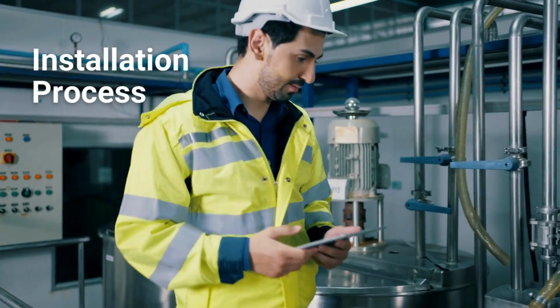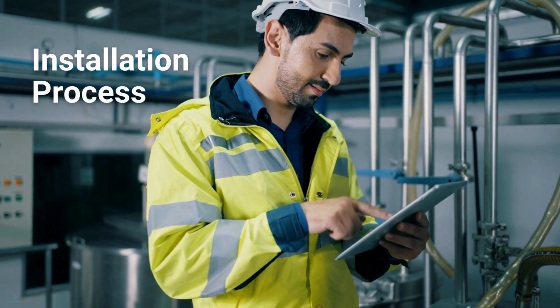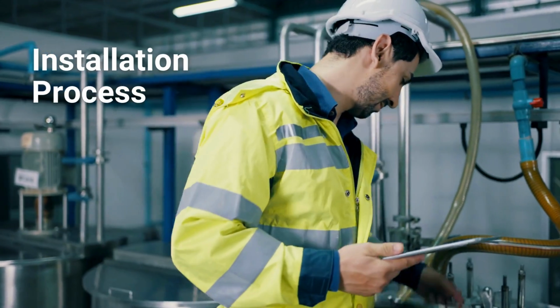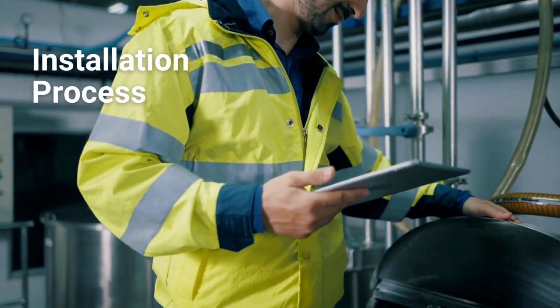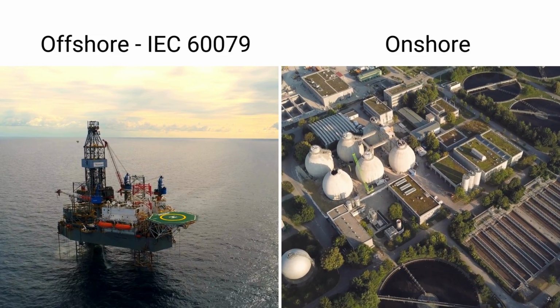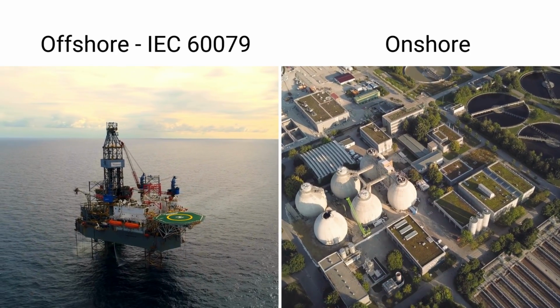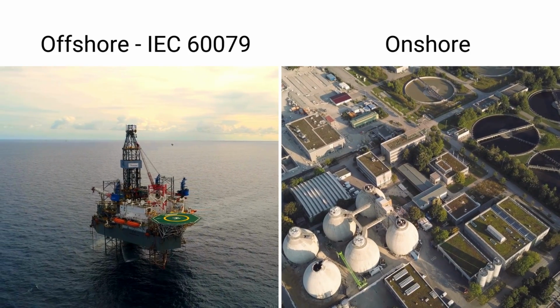Next up is the installation process. Once the design is finalized, the installation phase begins. This requires meticulous planning and coordination with various teams, including electrical, mechanical, and network engineers. For offshore environments, compliance with international standards like IEC 60079 for explosion-proof installations is mandatory. Certified equipment is installed to withstand these challenging conditions.